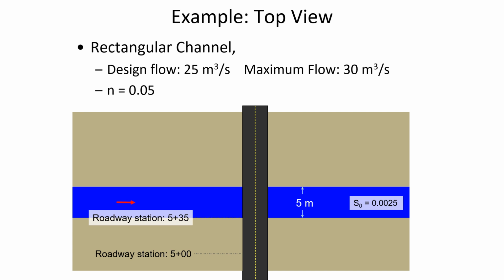If we had a trapezoidal channel and we're going to put a culvert in, and here's a road on top of it, so here's the asphalt, the crest length would be this distance. It needs to know that because it's going to be doing some weir calculations to find out how well the water's flowing over the top of the road.